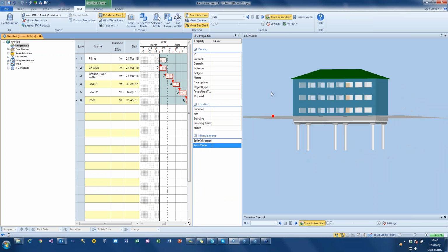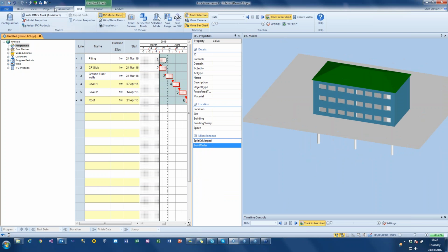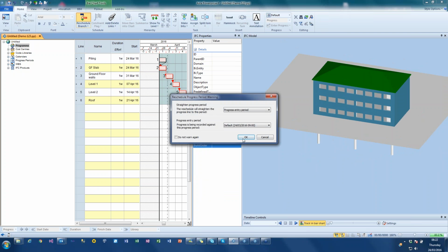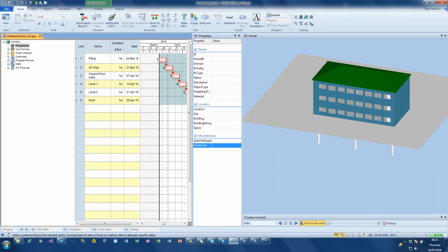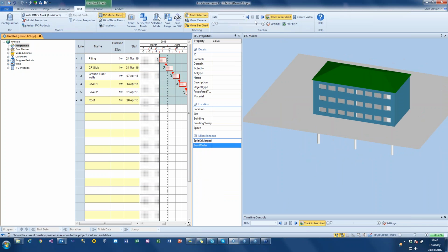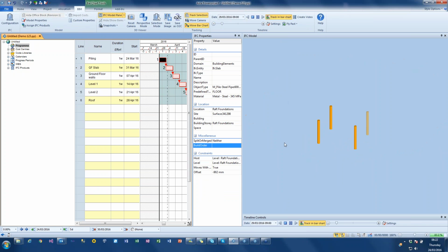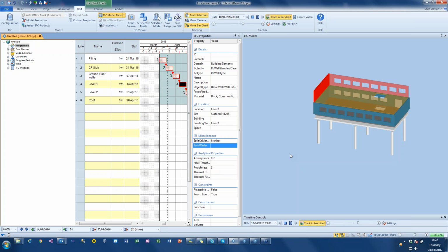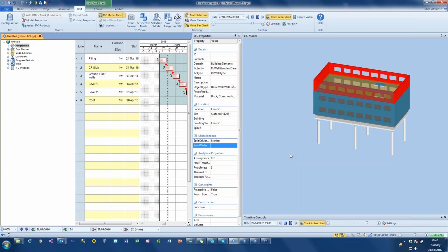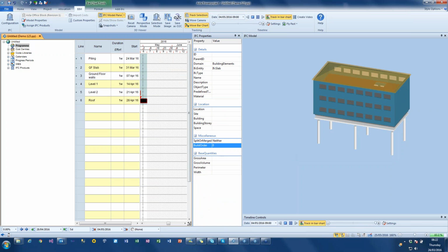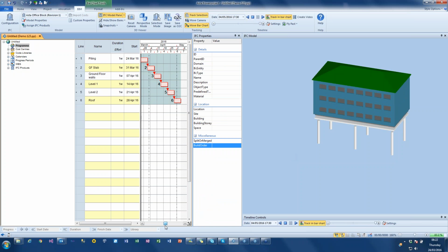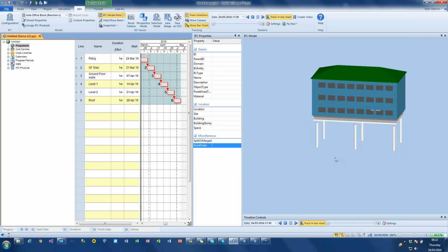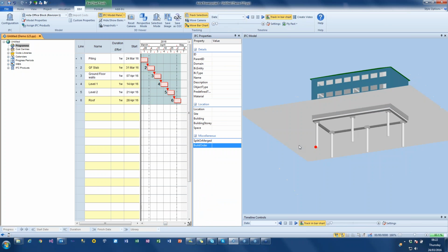By doing that, now what I can do is a reschedule in there, and then if I play this from my BIM side, you see you have the sequence of columns going in, then the walls go in the sequence that they're being built in, and so forth. Now obviously I'd have the still frame added to that before that, but it just gives you the principle that very quickly you can set this and put this in. Now I'm just going to stop that for a moment.